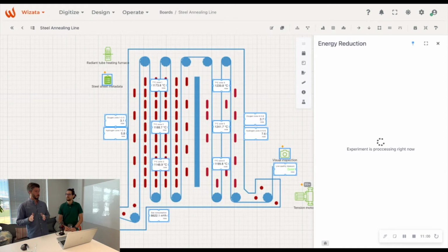And second step, for each of these contexts, we will go through all the data and check if we have some specific combination in chemical composition and gas atmosphere in which we could lower the temperature a bit and still have good quality results, because we filter it. So we have a label on the data that this consumption is good or bad.